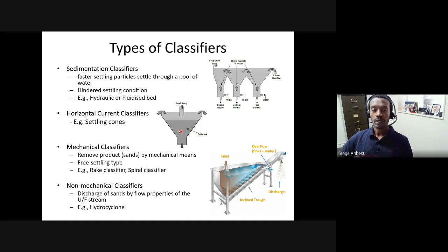As the solids accumulate and build up over time, you will have at least two zones. The first zone, or the bottom zone, should be mainly made from solids, so it's a sediment. And then you have an overflow region. As you continuously feed, the material should go somewhere. So eventually, as soon as you reach a certain height, the sediment will push and exit through the discharge.